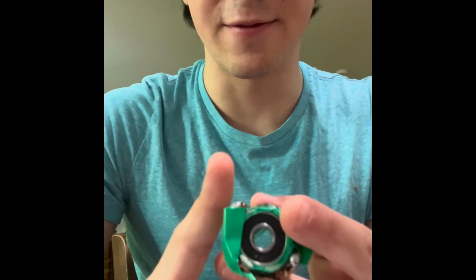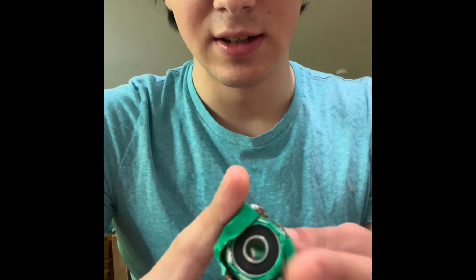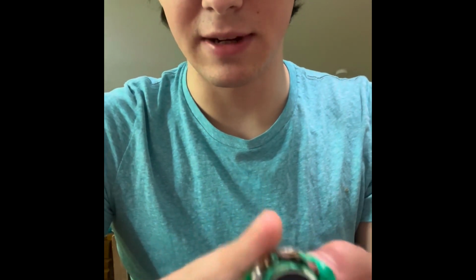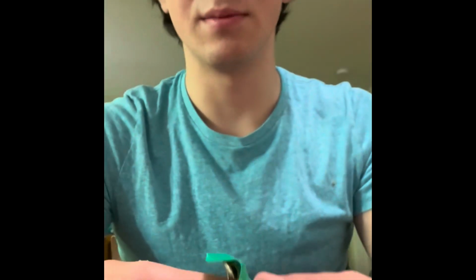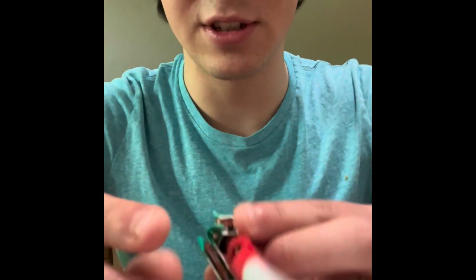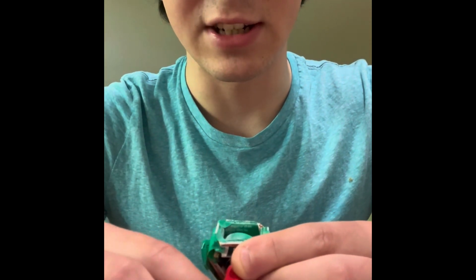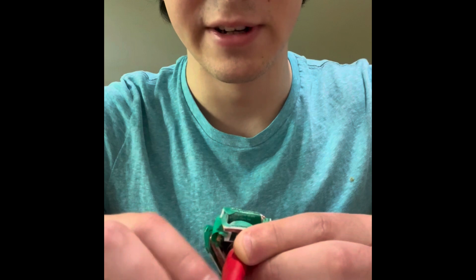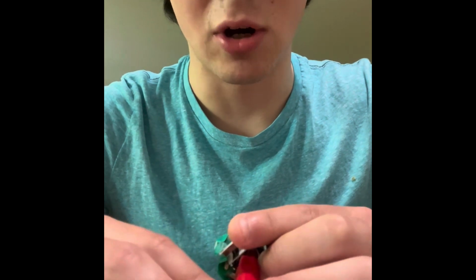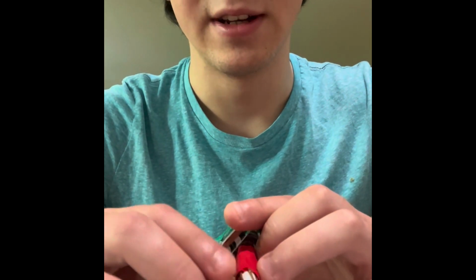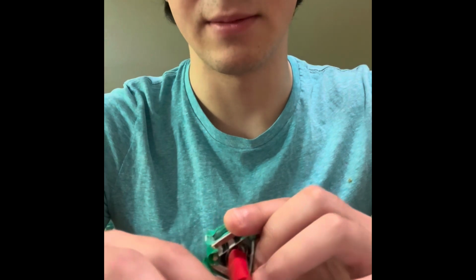I realized that the friction that the brushes had is going to be high no matter what, but on here especially it was extra high, not only because these connections were really messy, but because the radius is so large, the torque caused by the friction is a lot. So I decided after some research that a better option would be just attaching it to the sides like this. It's much simpler and it's much smaller, so the torque caused by the friction will be much less.